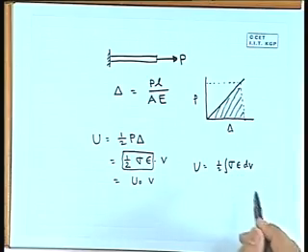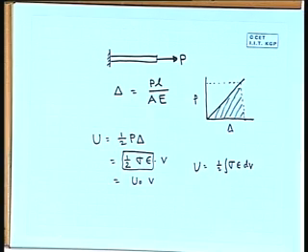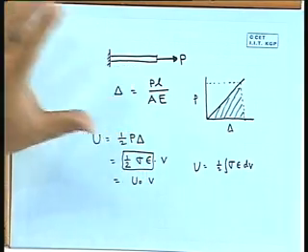Now, this is a case of uniform stress and strain. So, everywhere your sigma and epsilon are constant. For a general case, we have written U equal to half sigma epsilon dV, right. Whereas this was written for an arbitrary type of problem where stress and strain will vary from point to point. So, this is valid for this problem where stress and strain are uniform.